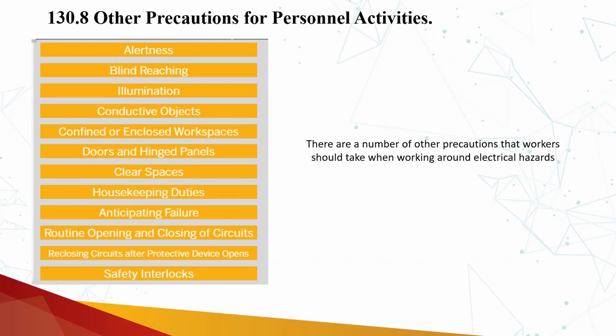Then reclosing circuits after protective devices open. This is one of the riskiest tasks, because once the device has opened, that means there was some failure there, a fault was there, and if you have not checked the complete circuitry, if you have not identified or found any fault, then reclosing circuits might result in another flashover or another fault, or it may be due to some transient faults which are being cleared when we are reclosing these circuits.